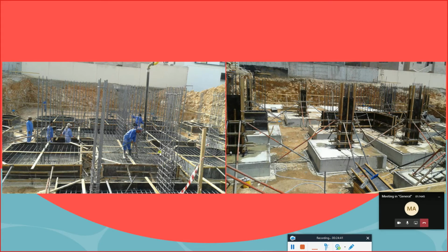Now after we finish the concreting, we will go for the curing of the foundation. You can see here we have the water still, so we need to spread water each and every day. When it comes to concrete, especially if it's a structural concrete, not a BCC, we need to spray or spread water above the foundation or above any concrete element.